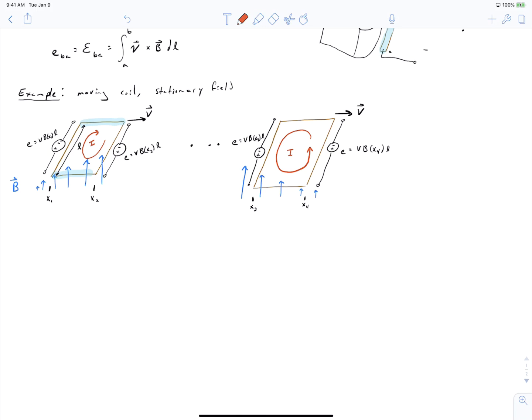All right, that's great. Now let's talk about electric motors. In AC machines, our coils are stationary, but our field moves. Our field rotates counterclockwise, the way we've defined this. And so this would be the same thing as saying that our field is stationary, but our coils are rotating clockwise. So it's the relative motion that counts.